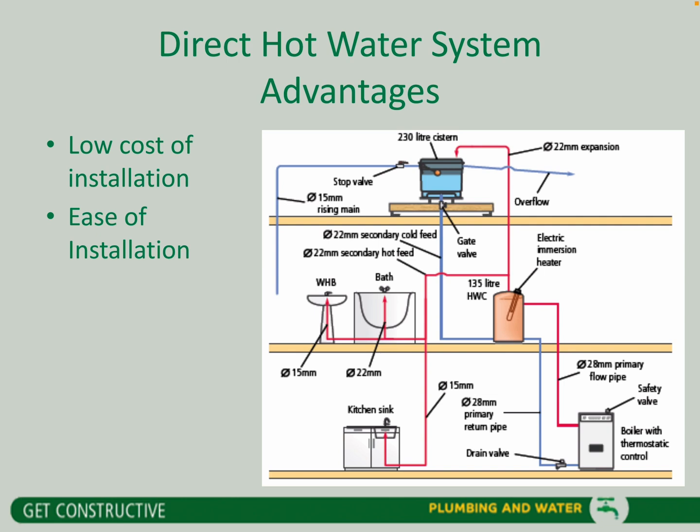What we also have down in the bottom right, you can see there we have a boiler. It also says there a thermostatic control. Basically it means it's going to cut off at a given temperature. Most of us humans, we can't go along and have a shower in 100-degree water. That is steam. What we generally have is about a 40-degree shower, if not 38. So it's important that we don't overheat the cylinders. That's where the boiler comes into play.